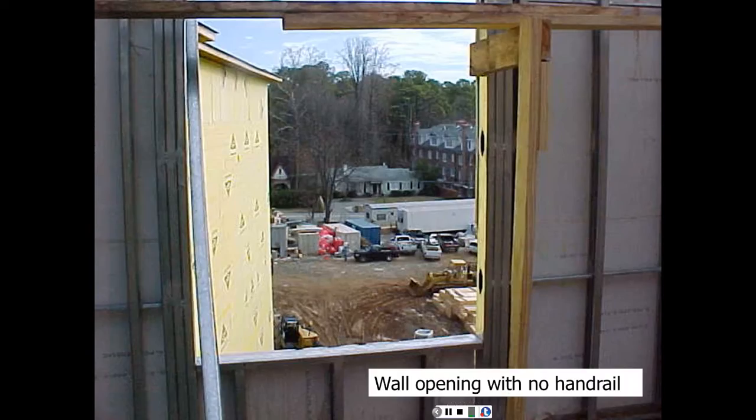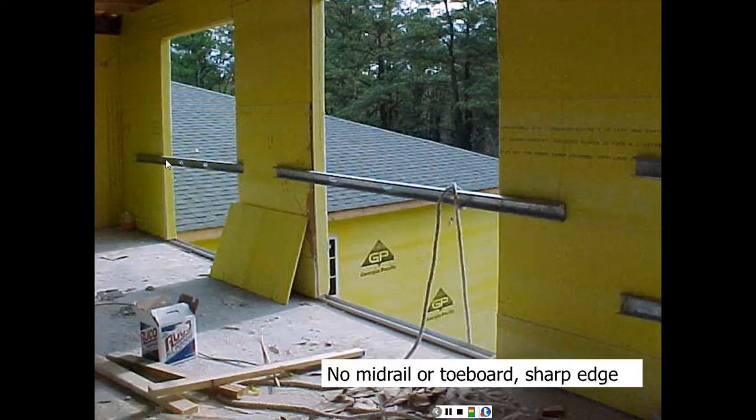Here we have a wall opening with no handrail. If someone is leaning out of this window to do any work, they may fall. Here we have a top rail, but no mid-rail and no toe board. And even with the top rail, it's like a C-channel, like a metal stud. So yes, it can resist the 200 pounds, but it has sharp edges which might injure the person it's trying to protect.